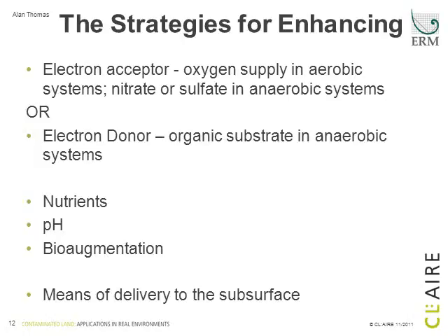Also, we may be seeking to add nutrients, optimize pH, and occasionally as well we may be looking at bioaugmentation, which is the introduction of microorganisms to the subsurface, and again I'll talk a little bit more about that later on. But ultimately as well then we need a means of delivery to the subsurface, as we said, getting these things into the ground in the right concentrations where the contaminant is, to really optimize biodegradation.